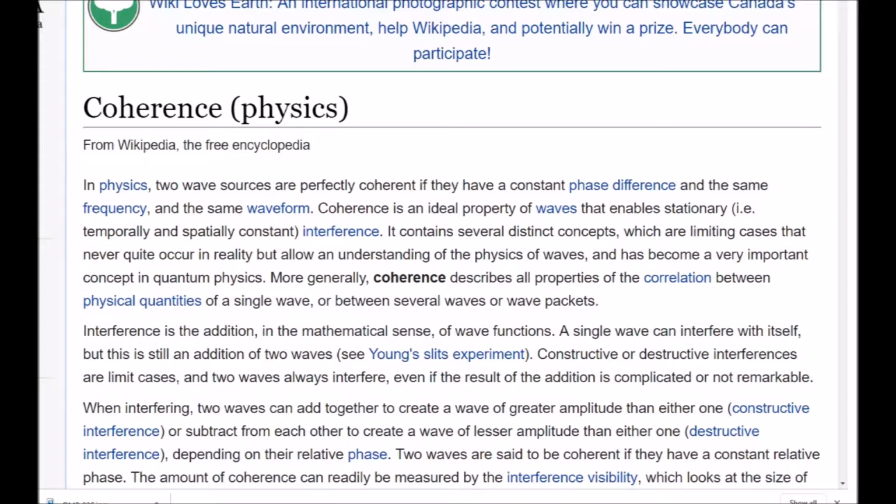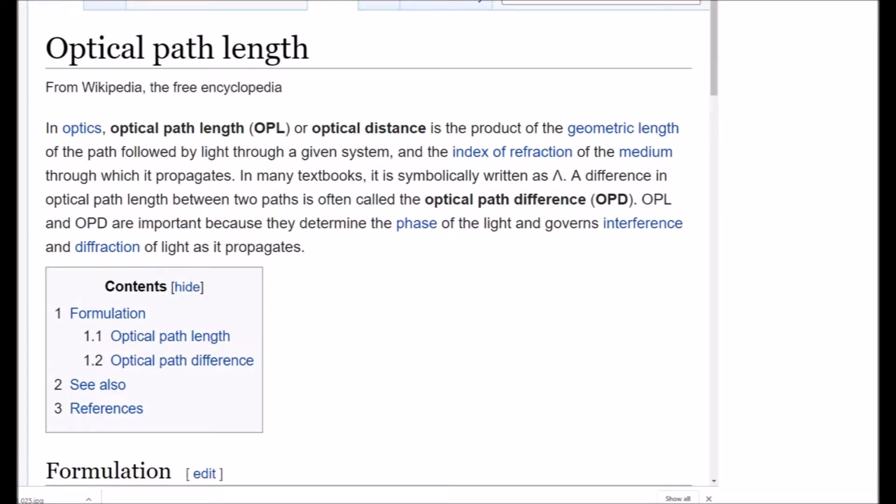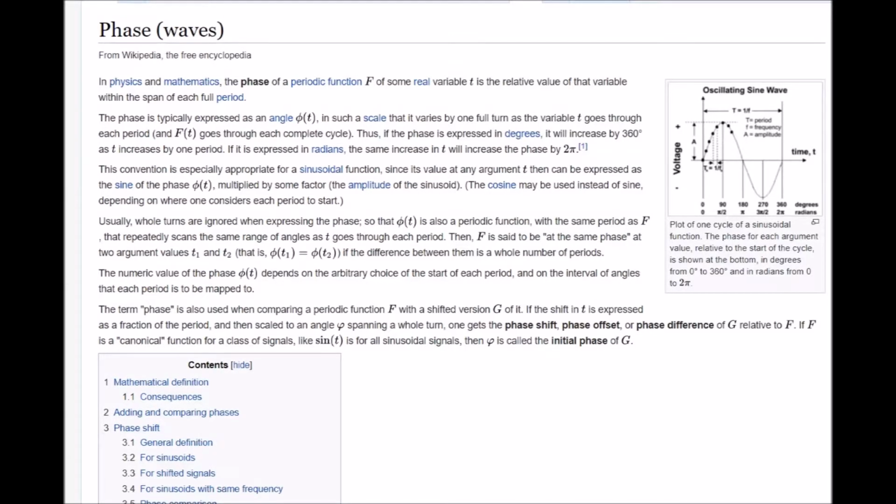The interference will arise owing to the 2 or more components of the wave having, in general, traveled a different length as measured by optical path length, geometric length, and refraction, differing optical speeds, and thus arriving at the detector out of phase with each other. The signal due to indirect paths interferes with the required signal in amplitudes as well as phase, which is called multipath fading.